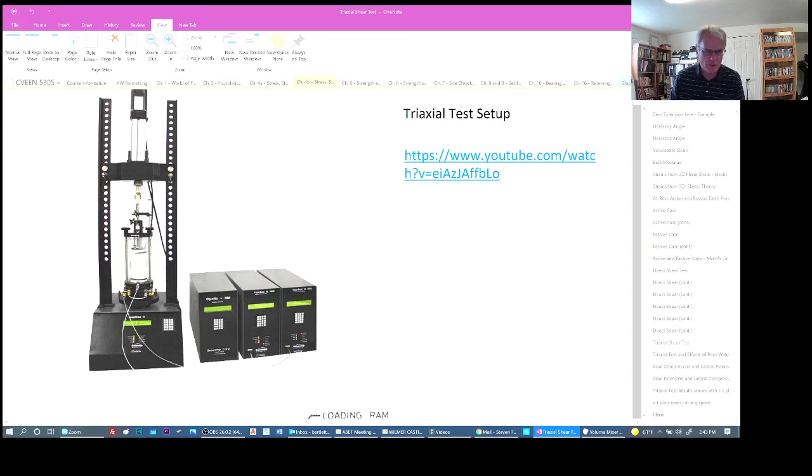Again, the deviatoric stress, we start pushing downward on the specimen and causing it to compress, and then measuring the force versus displacement and trying to find the peak force and resistance. Quite often, like we saw in the direct shear test, this will pick up a considerable force and then eventually it will reach a peak and then drop off. So that describes a consolidated drained test.